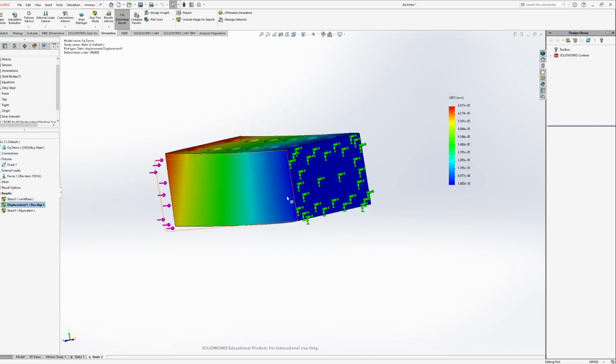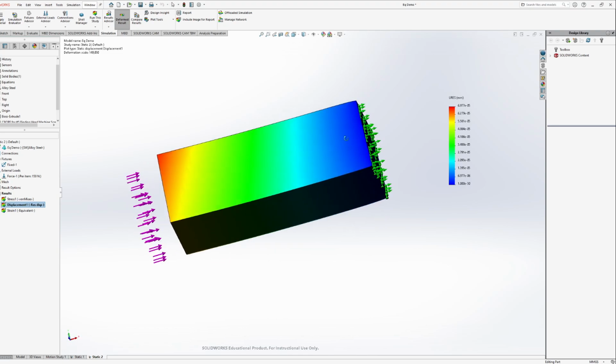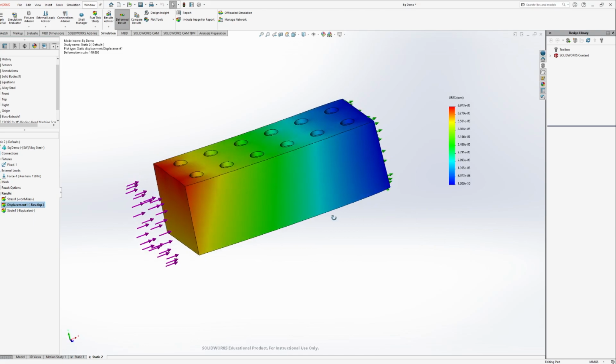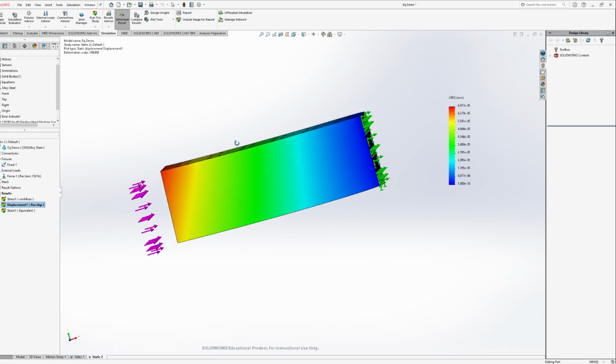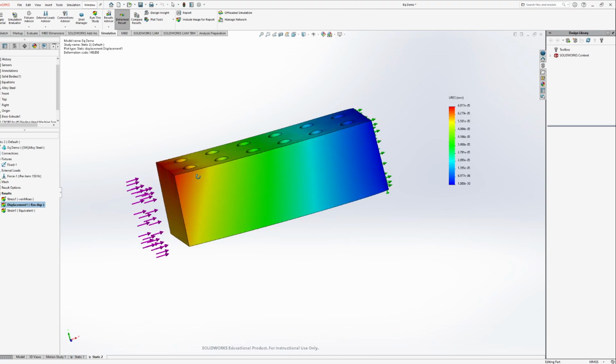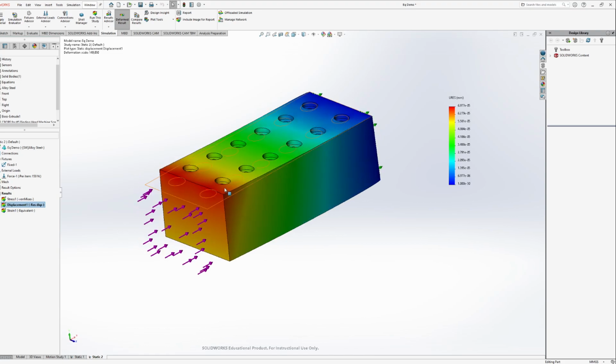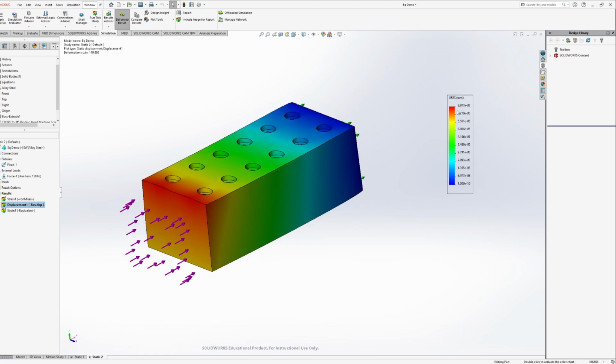So keep in mind, these are numerical simulations, so it is calculating a number here. It's not using logic. So that's where you guys need to kind of step in and say, if you add that to a paper or something like that, you might have some people furrowing their brow and saying, okay, well, it's zero. Let's be real here. It's basically zero displacement, and it displaces on an order of just shy of 7 times 10 to the negative fifth millimeters, which is also quite small, ridiculously small as well.